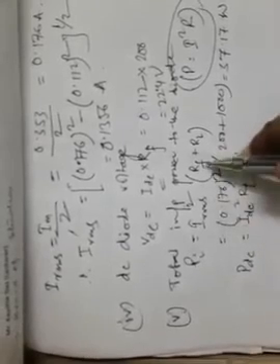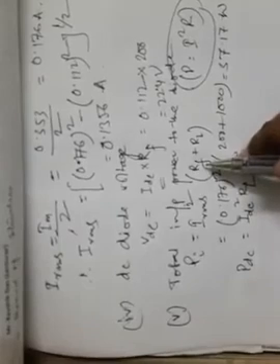At the output of the diode there will be no question of considering the internal resistance of the diode. So the resistance part will be having only RL. So IDC square RL is the output power from the diode, or output power at the load, rather we can say, from the diode.